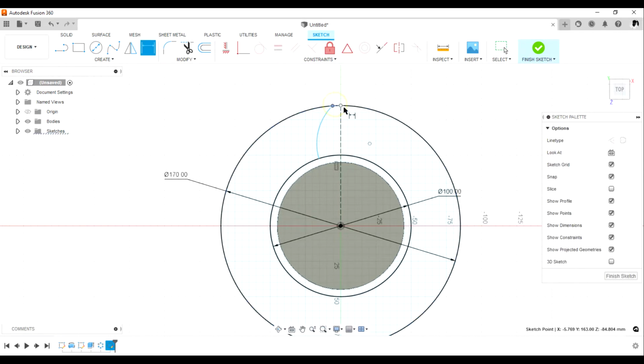We'll just draw the first section, then we'll mirror it to the other side. That is 40 divided by 2. Then we can now add the radius. Radius is going to be 65 from that diagram. Then you can go ahead and mirror it.